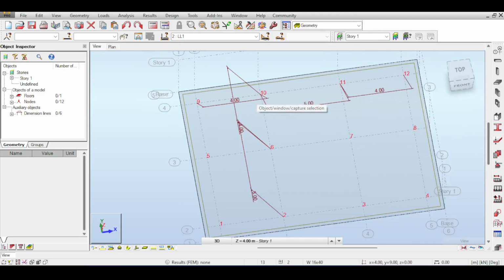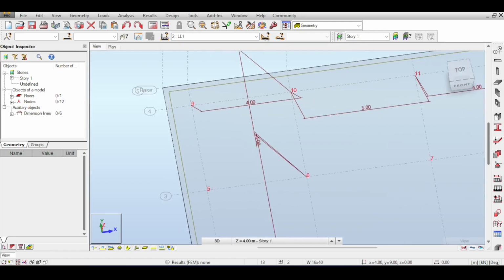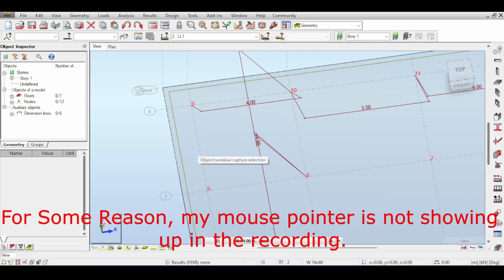The reaction method is what you use when you model your full structure. So for this 9-meter column, the tributary area is going to be 2 meters here. It has a tributary area of 4 meters, which means that its live load for 1 story is 4 meters square multiplied by 4 kilonewton per meter square, which is 16. This is for 1 story. So I write the number 16 here. And for dead load, it's 4 by 10, which is 40 kilonewtons for 1 story.